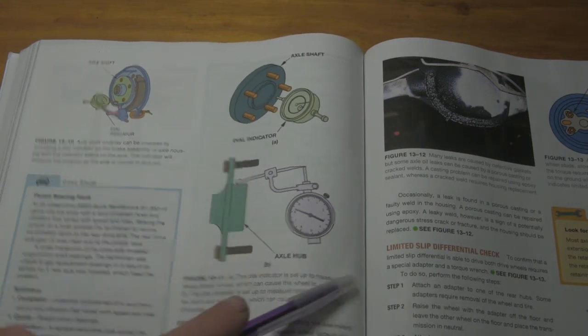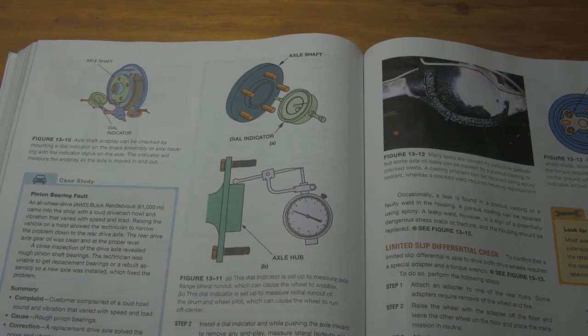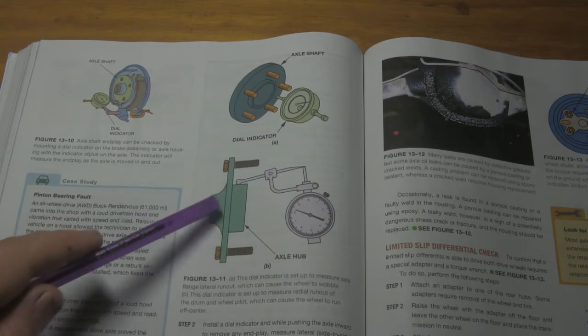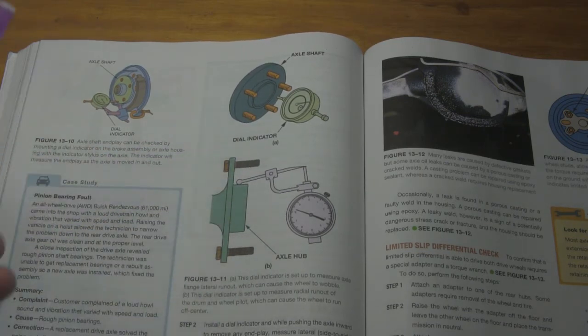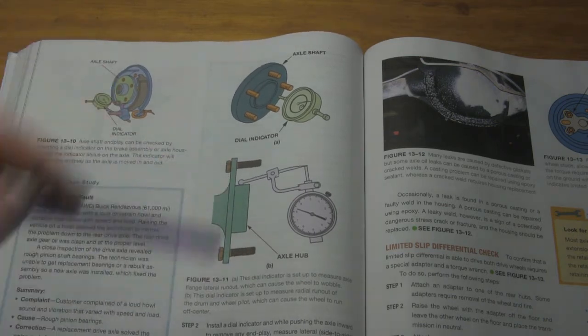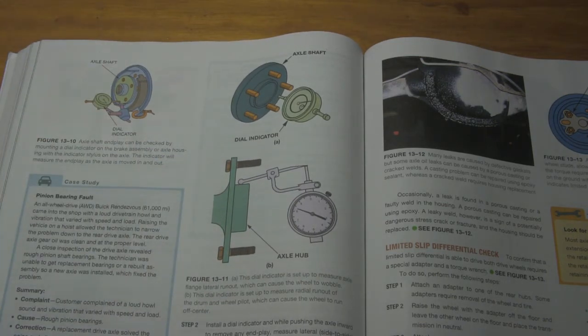And so in this illustration here, we're not measuring the axle tube, we're measuring out at the flange for any type of walking that's happening. And so if we have an axle shaft that's bent, you'll see that bend in a wobble out on the wheel side. And so if you have a customer that's complaining of maybe like a vibration issue or a shake issue, or maybe they're just chewing up brake pads because they have a disc brake rotor in the back, you can spin that wheel, and sometimes you can visually see it, but if it's not really bad, you might have to put a dial indicator on it.